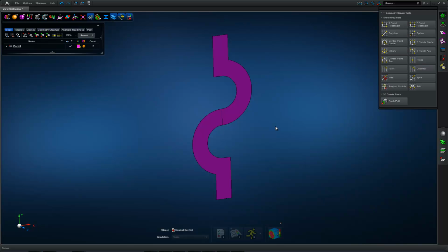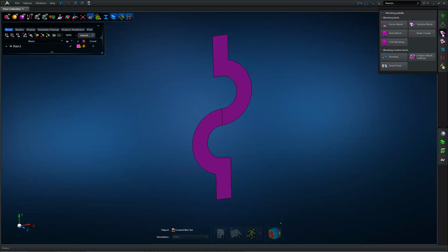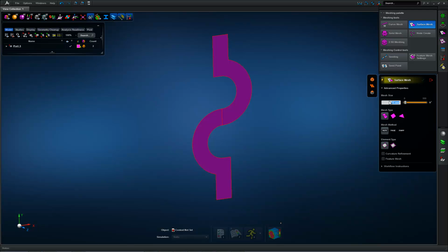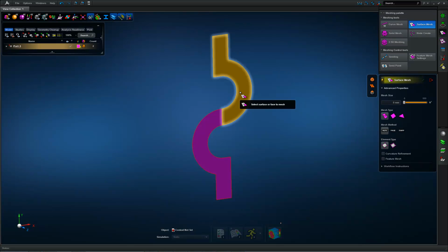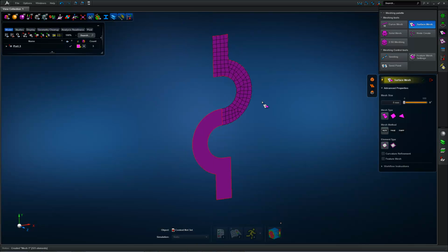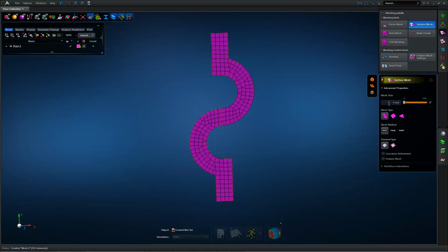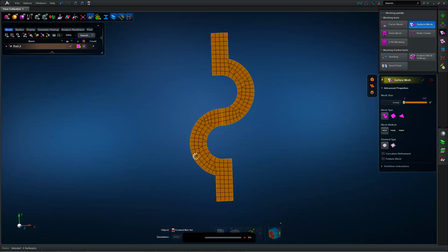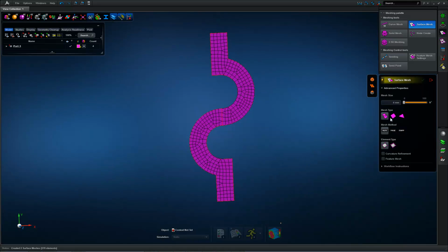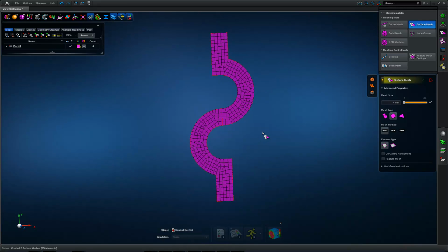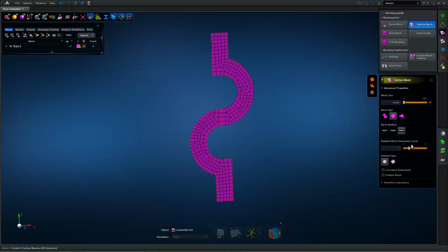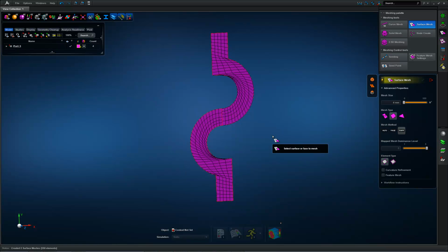Now let's proceed setting up the finite element model. The very next step is to create a mesh for our surfaces. We can start with a default mesh of 5 millimeters and see what the quality of the mesh looks like. This doesn't look too bad, so we can use it like that, or maybe use a finer resolution just to check what that does. We can play around with various options and various other parameters to see if this helps us at all.